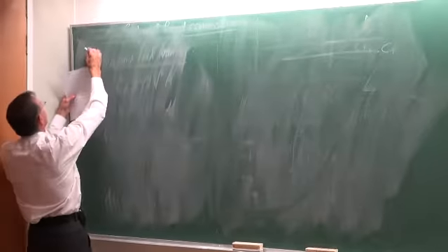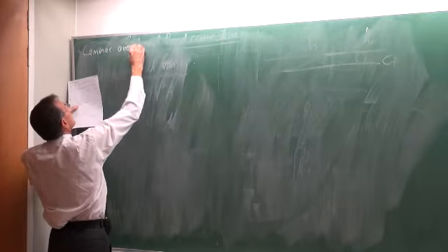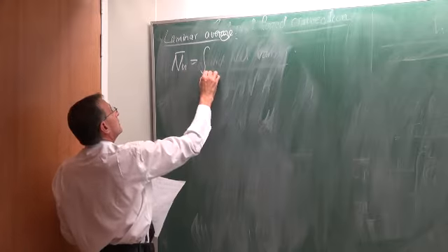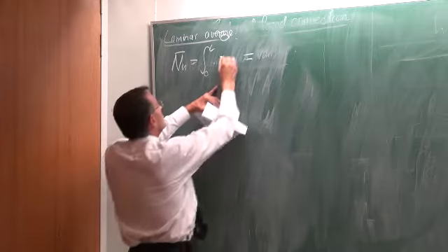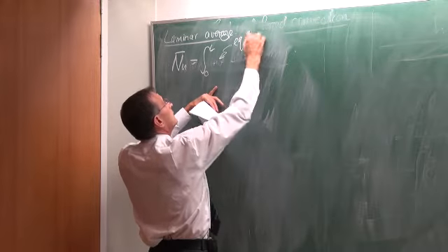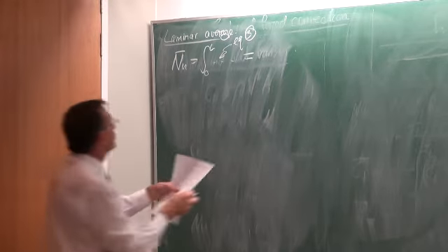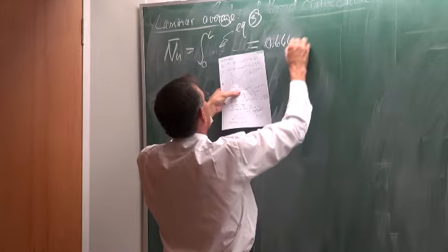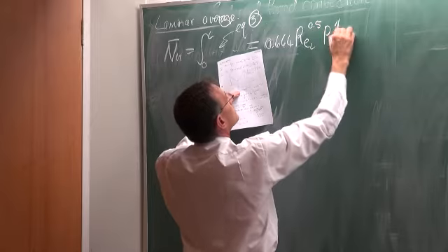So if we now look at laminar flow average, which means that we have to take now the Nusselt number and do the integration, and the equation that is going to be used in there would be equation 3, the local value for laminar flow that we do the integration for. The result is that the Nusselt number is equal to 0.664 Reynolds to the 0.5 and Prandtl to the third.